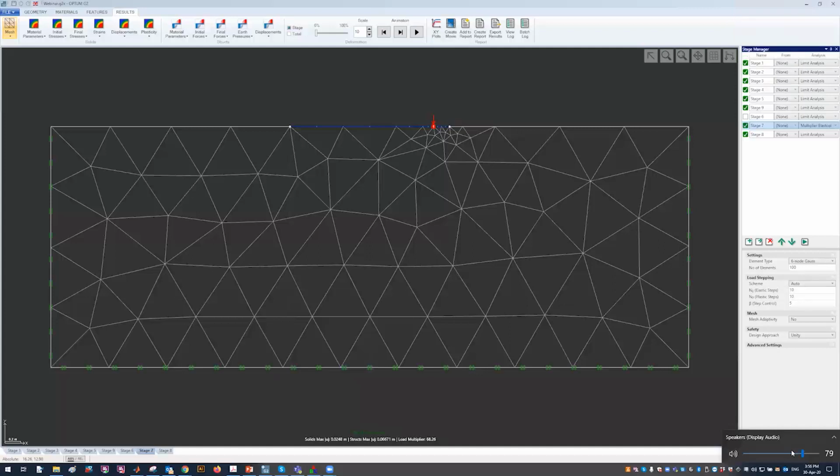That's good, because one of the problems that we are having here with a Mohr-Coulomb model is that the unloading modulus is assumed the same as the loading modulus, and that's why in this type of situation we use a hardening soil model, and convergence is usually better. We typically use Plaxis for that, and just wanted to see if you would recommend this software as an alternative to Plaxis.